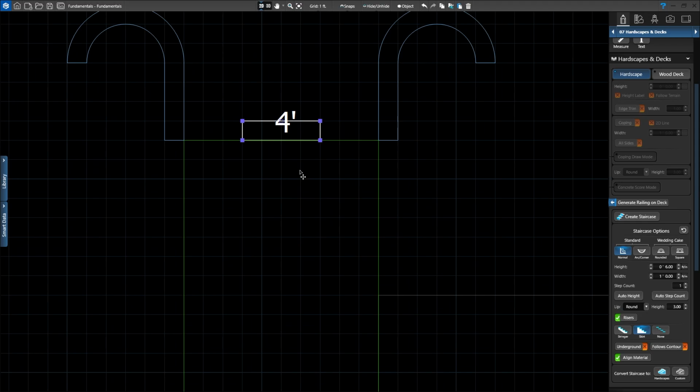The stair building tool has modification points like other shapes, but they work a little bit differently. The outer points move independently, and the inside points that are touching the shape will stretch the steps proportionately. So I'm going to left click and drag the bottom right hand point all the way to the right so it snaps onto the handrail on the right. Same with the bottom left hand corner. Left click and drag to the left until it's even with the handrail.